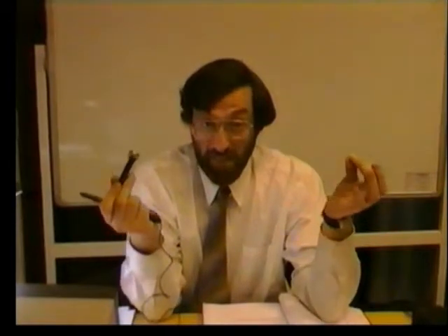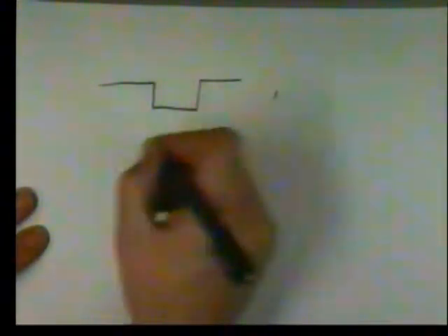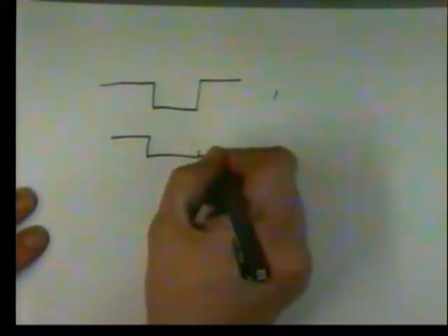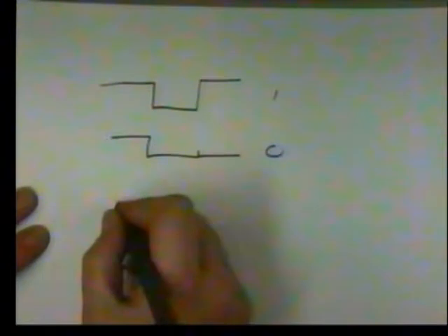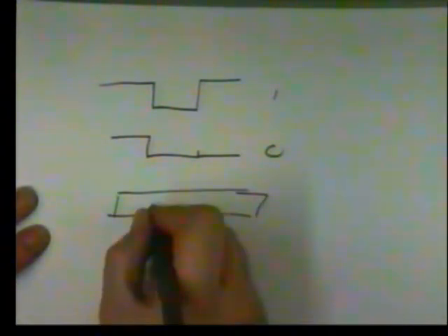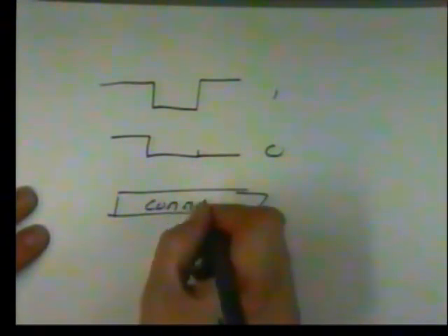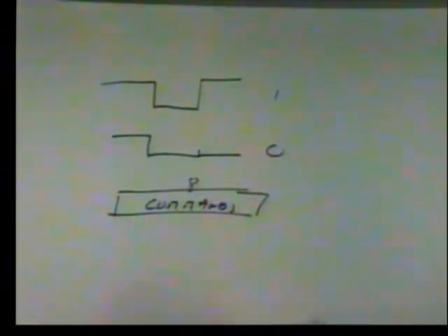That standard is published and is freely available for anybody to use. The way it works is that we have logic level 1s and logic level 0s, and these are grouped together into 8-bit commands. So 8-bit commands are clocked out.